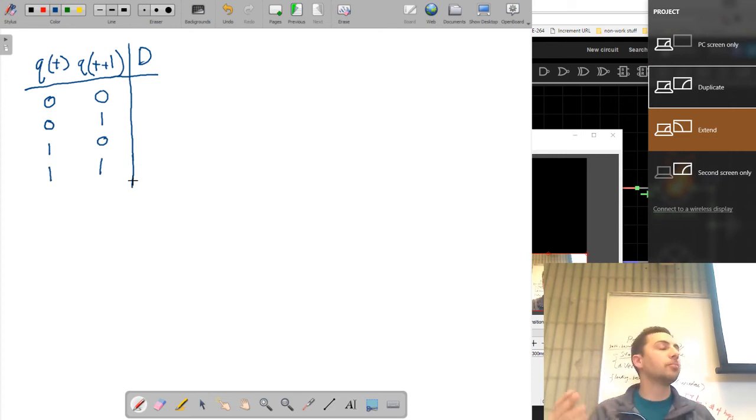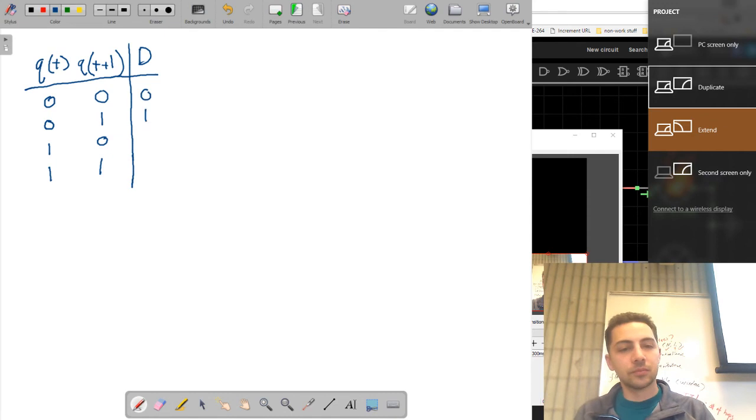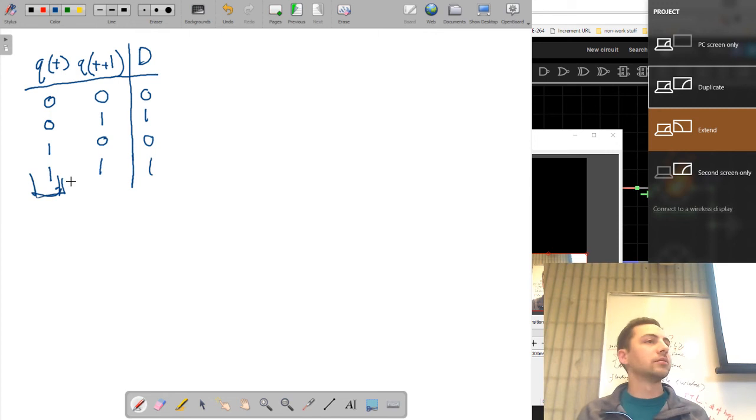What do we need to put on the input for a D flip-flop? And D is kind of the counterintuitive one. We haven't talked about excitation tables yet because they're so mind-numbingly counterintuitive. Here's the excitation table. Okay? It doesn't matter. This column just does not matter. The only thing that matters is where you want to go for a D flip-flop.